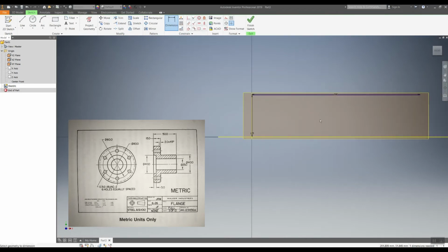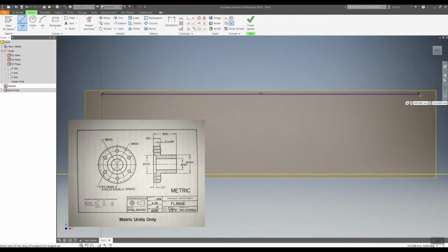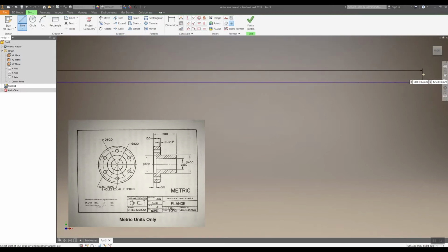This is the start of my flange right here. That takes me up into that point. How thick is this? Well, it says 400, and if we subtract 400 by 250, that is going to give us 150. We divide that in half because we need a radius. It is 75. Now, kids, here's a little helpful hint. Zoom in to get this.